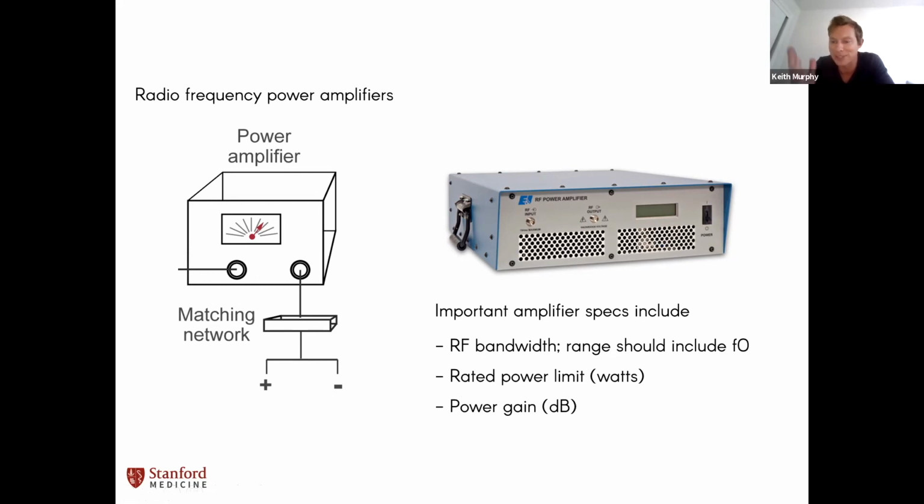So Kim and I were just talking about somebody asking for an amplifier that might need like 500 watts. This amplifier in particular is only 100 watts, so it wouldn't be sufficient for their application. So you want to know what power you need. And you also want to know the gain. This will be for voltage or for power, but this one's a 53 dB amplifier, so you can take your voltage input and ask how much that's going up.